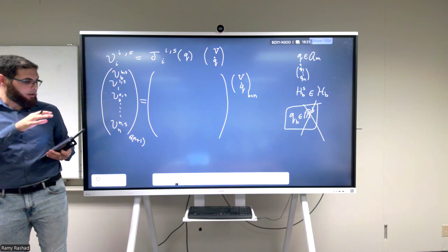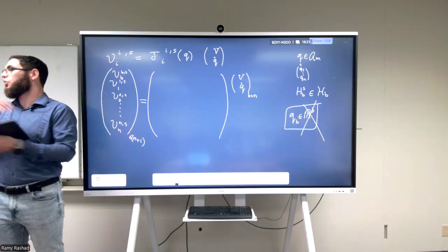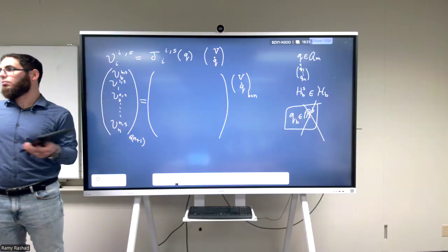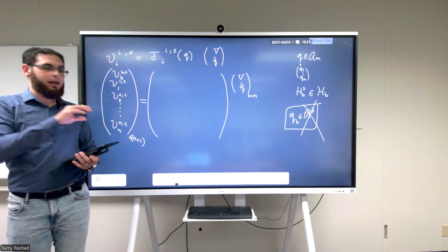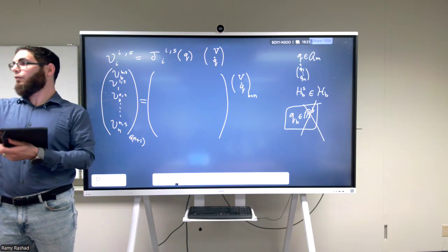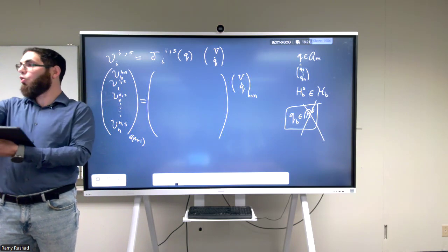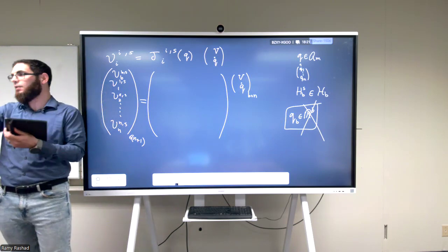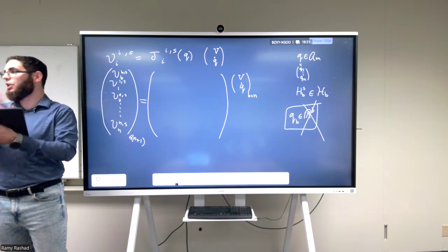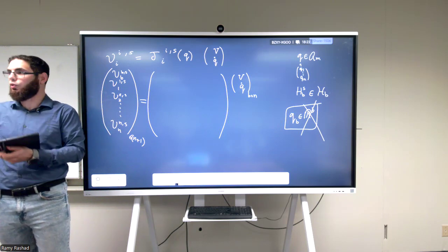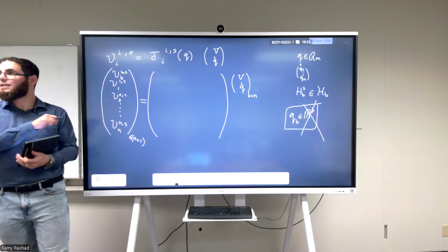And depending on the number of n, we can classify the robots. You can talk about redundant manipulators or non-redundant manipulators. If you have a fixed base manipulator, the minimum number of n that you need to have full actuation on the end effector is 6. And this is why when you have a 6-link manipulator or more, we call this a universal robot. It can apply a wrench in 6 dimensions. If you have less than that, then there are some directions you can never touch. You can never actuate or go there, if I'm talking about a fixed base manipulator.